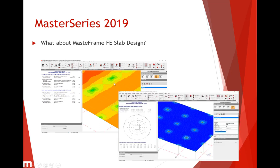So we had a screenshot there of some peak moment or peak design over a column head, with an interface for specifying the amount of reinforcement. A lot of thought has gone into how the workflow is presented, in terms of basic bars plus additional auto design bars, or whether you want to do auto design at all, all of which then leads into a punching shear design. It's shaping up to be a really nice interface and feature set for MasterFrame flat slab design.